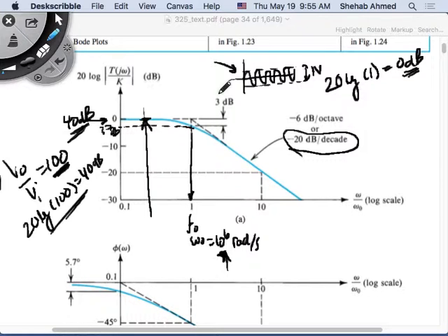What did you say, 0 dB? It will do that at this frequency, which is F naught multiplied by 0.2, for example. Now, I'm asking you, when will the output signal look like the input signal? The input signal is 1 volt. Exactly. Where is this 0 dB going to happen? At what frequency will this 0 dB happen?